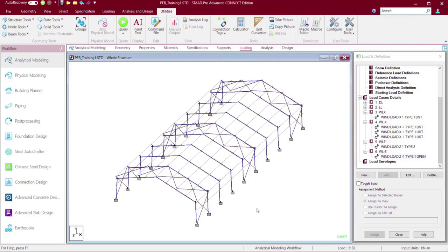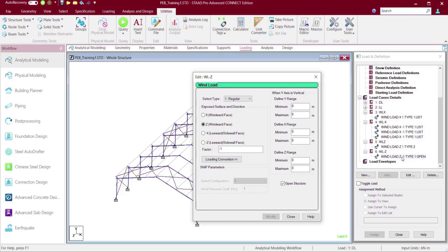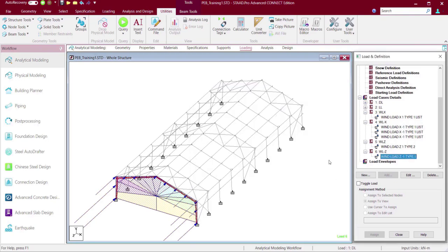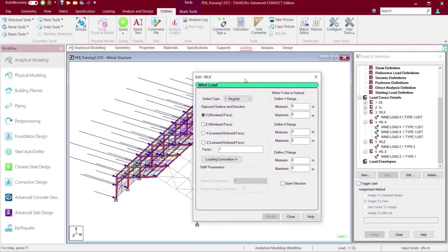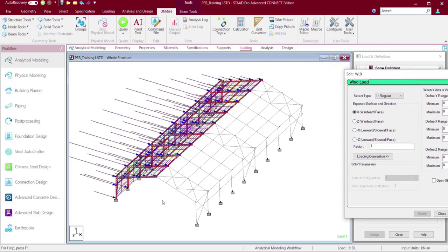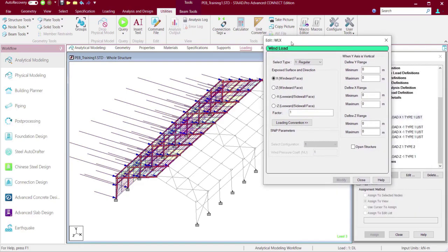So we have different options, as I mentioned, like windward and leeward. These are very useful if you are considering finer effects like the suction force due to Bernoulli's effect. When the wind is blowing over the slope portion, due to the increase in the velocity of the wind from this aerodynamic effect, the roof is very susceptible to getting blown off.